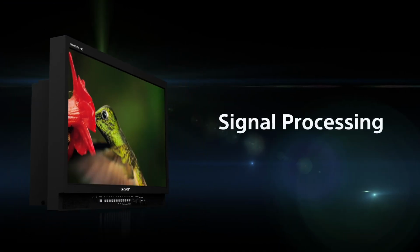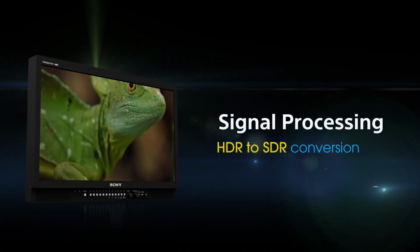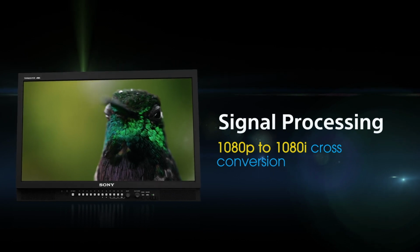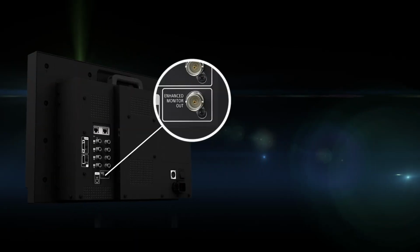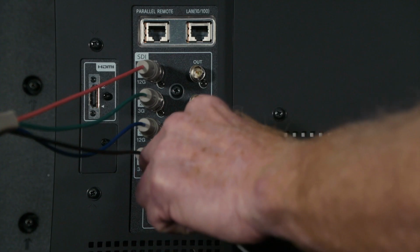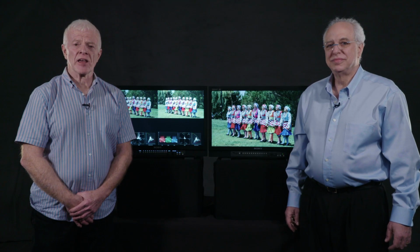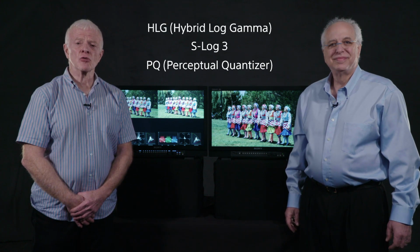In addition to HDR-SDR conversion, the license will enable the following functions: 4K to HD down conversion, 1080p to 1080i conversion, quad split 4K signal into a single cable 12G format, and a process output via the enhanced monitor output, which can include the converted or baked-in LUT version of your program material. The HDR curves that are supported by the PVML-HSX1 conversion license are HLG, or hybrid log gamma, S-Log3, and PQ curves. So, let's begin this demonstration by examining how to use the menu in the HDR conversion process in the PVM-X monitor by simply selecting some of the conversion presets already pre-programmed in the monitor.